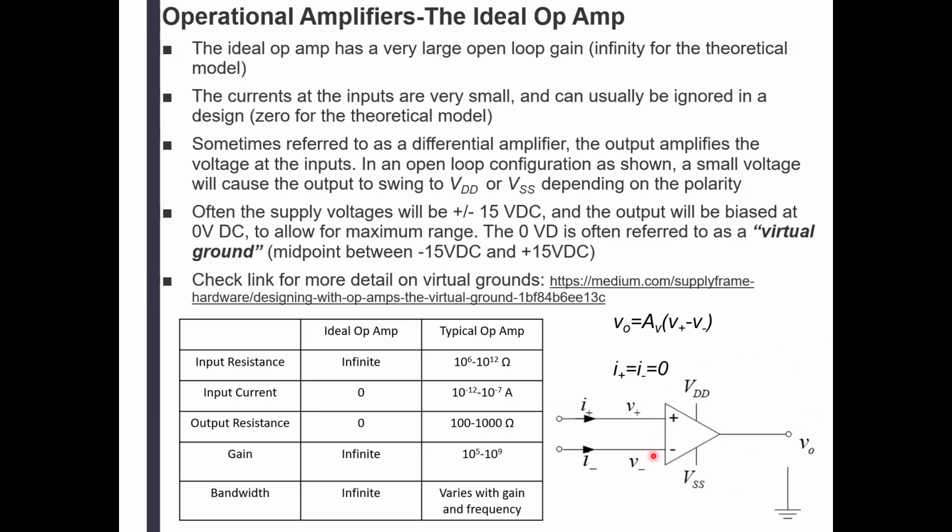Now, if this one right here is slightly higher than that one, it is going to go down all the way. And it's very difficult to sometimes accomplish slightly more than 0 and slightly less than 0 volts. So this is not a very stable circuit, but that's how it behaves.